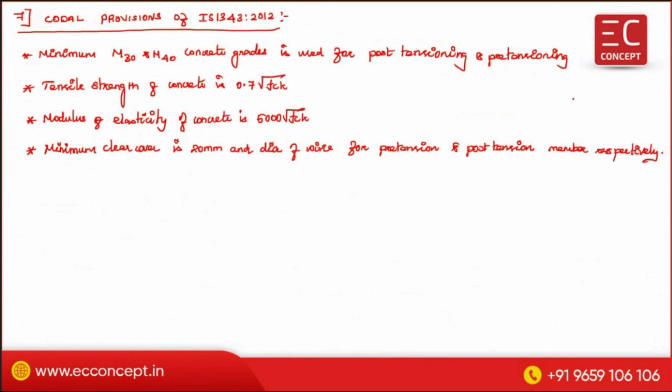See here, the minimum clear cover is 20 mm and the diameter of wire for pre-tension and post-tension member respectively. Therefore, minimum clear cover for pre-tension is 20 mm, and for post-tension it is the diameter of the wire. Okay.